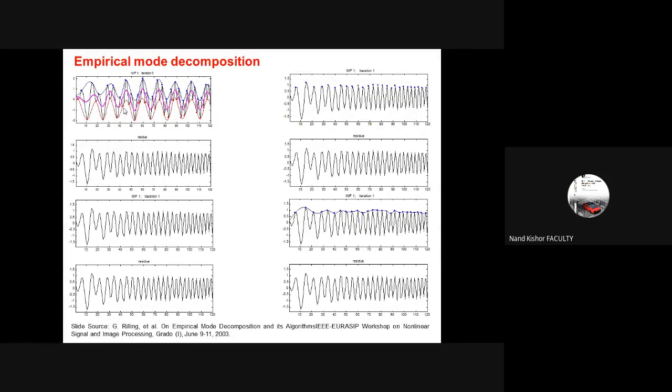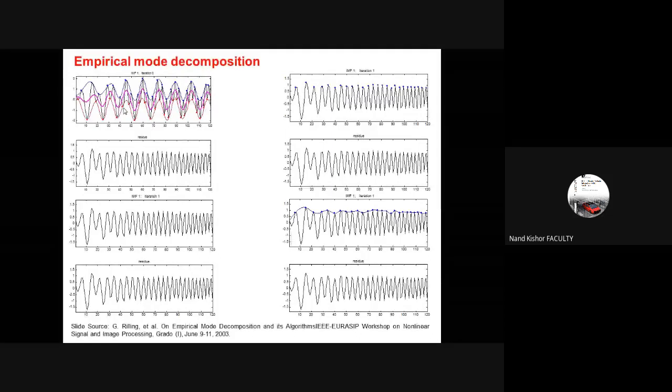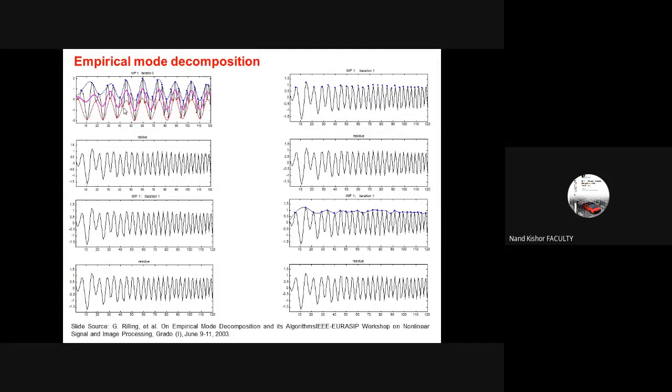Right? So it is very important. And thus in more complex signals, or signals of a non-stationary nature, and even with the presence of noise, the IMF which is decomposed is not exactly a monotonic component. That means it may have, let's say, a frequency component corresponding to 28 hertz, and it may also have another frequency component corresponding to 22 hertz.